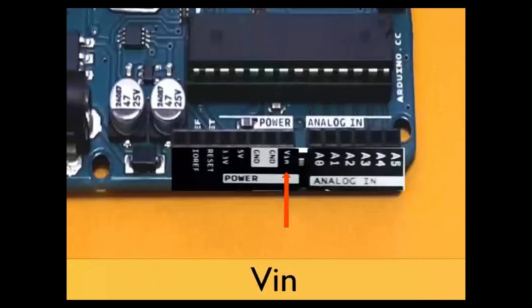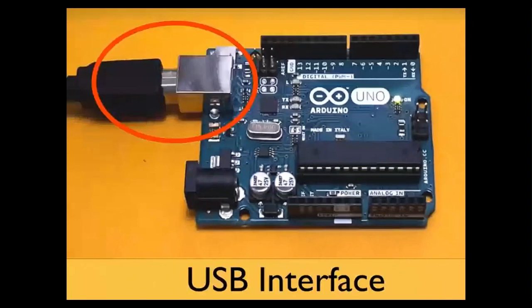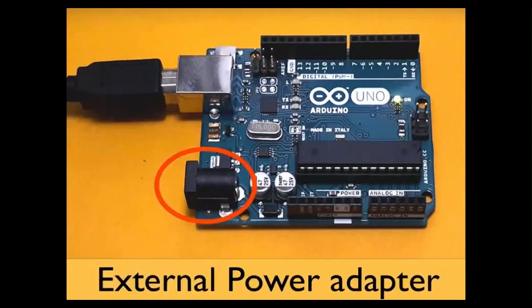This is input voltage to the Arduino board, when it is using an external power source. These are ground pins which give access to the lowest voltage on the board. USB interface can be used for programming the board and also can be used for serial communication between the board and the computer. We have this external power adapter to power up the board.